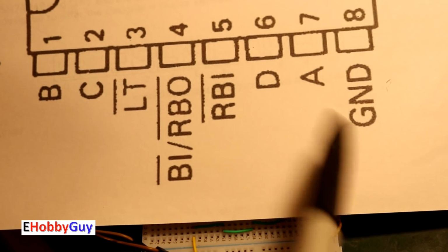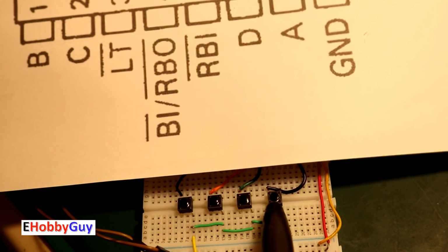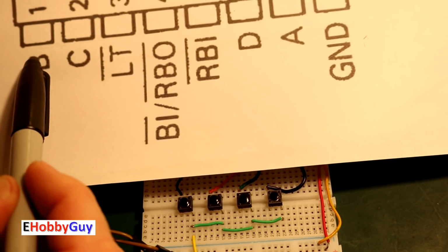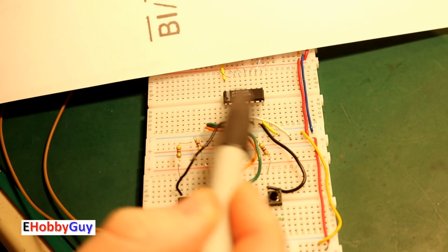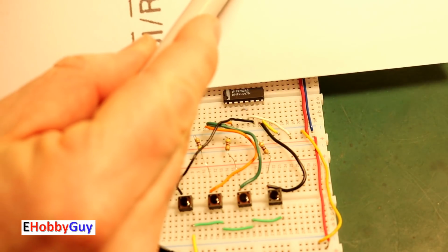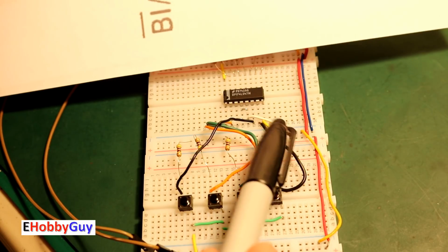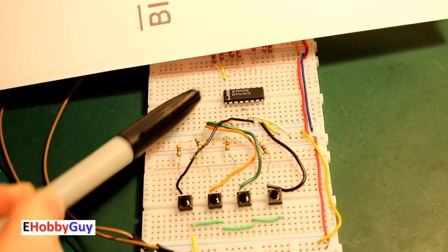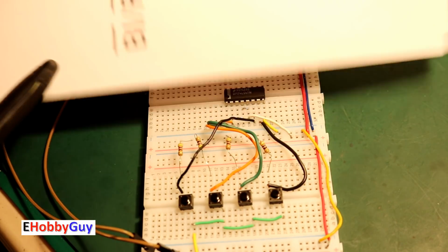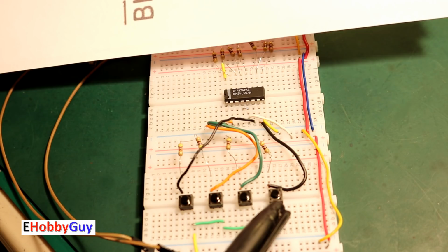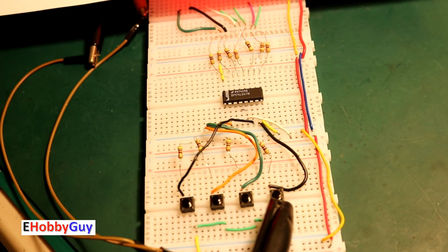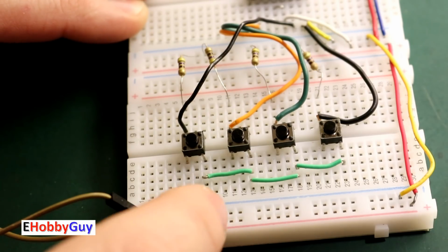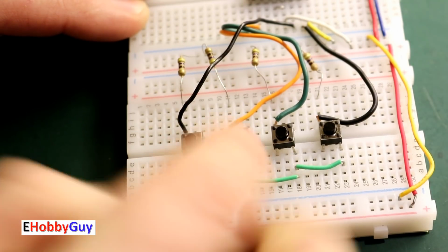Looking at the A, that's going to be all the way on my right. That's this button right here. B is going to go all the way over here. And so I have jumpers going to the chip right here. A is going to the second last pin on this side. That's the black wire. The B is going to the pin that's all the way up here. That's the green wire. Is coming up to pin number 1 on the chip here. So I want them to be in order as I'm doing the inputs. I want to be able to follow this and be able to easily count from 0 to 9. So I'm making them A, B, C, and D. I just wanted to make clear here what I'm doing with the buttons and how they're hooked up.